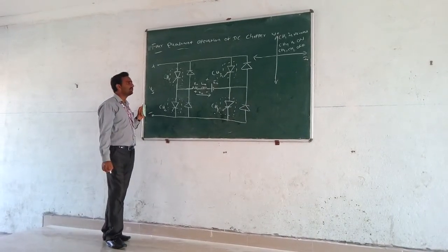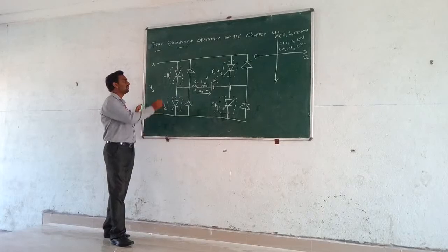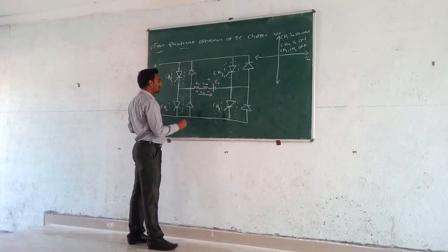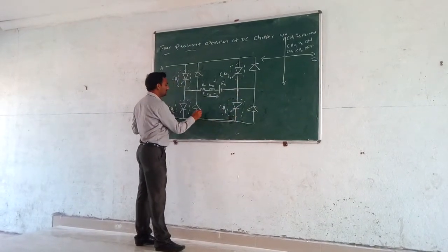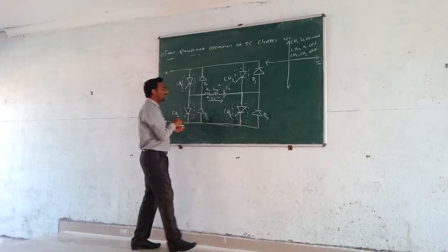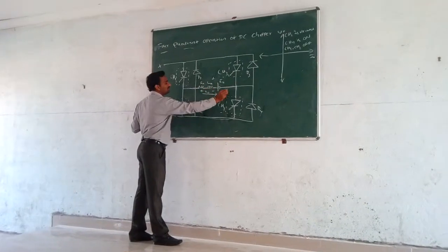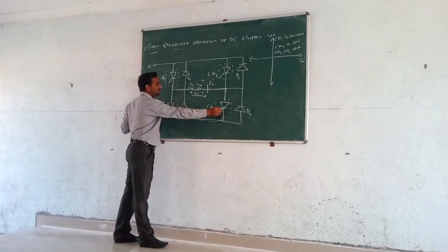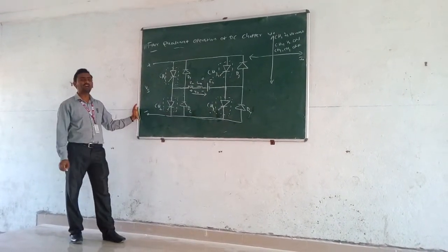Next, when CH1 is off, same quadrant, if we turn off CH1, at that time the current direction is from back EMF to CH4 to D2. The current flows in an inner loop consisting of EB, CH4, D2, RA. So the current circulates in this loop when CH1 is in off state.